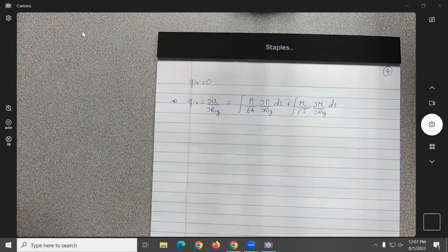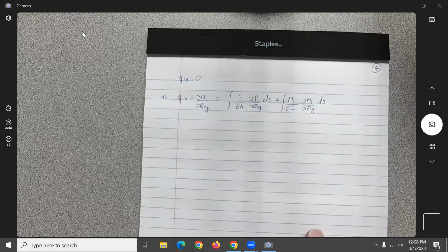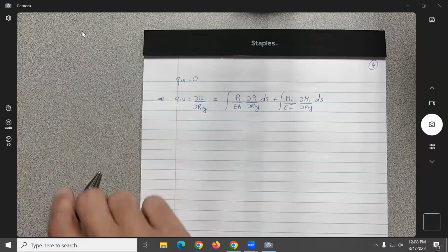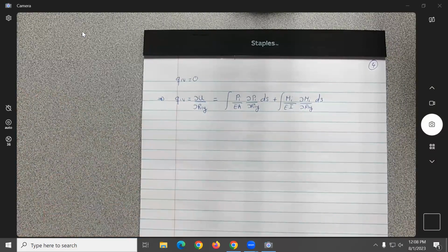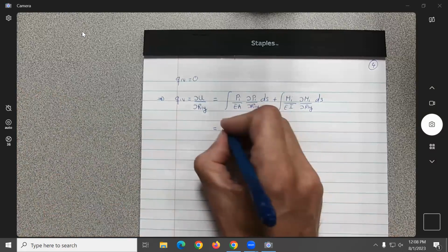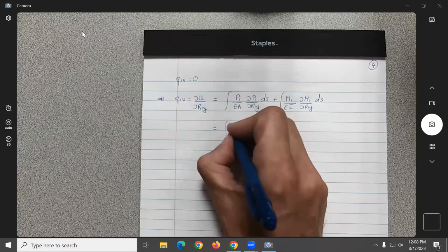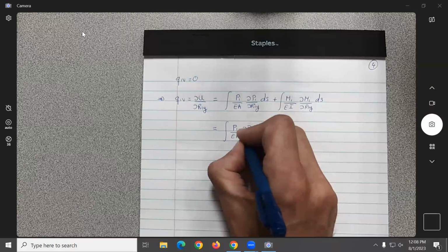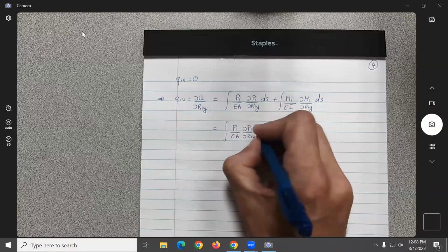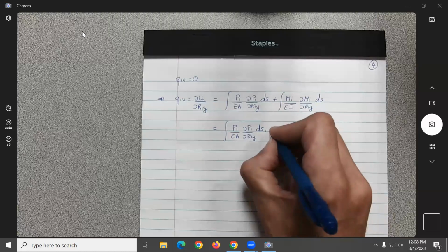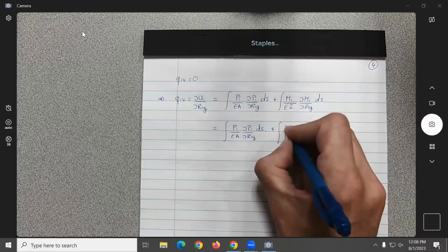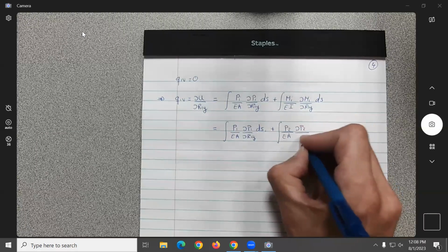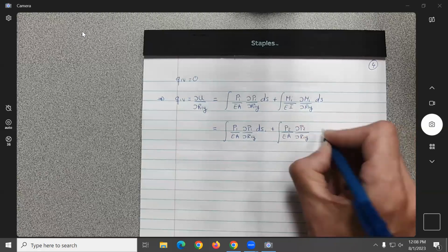Okay, I'm going to do it slowly, since it's the first time. So what should we have over here? We should have two terms for the axial terms: P1 over EA, partial P1 over partial R1Y, ds1, plus P2 over EA, partial P2 over partial R1Y, ds2.